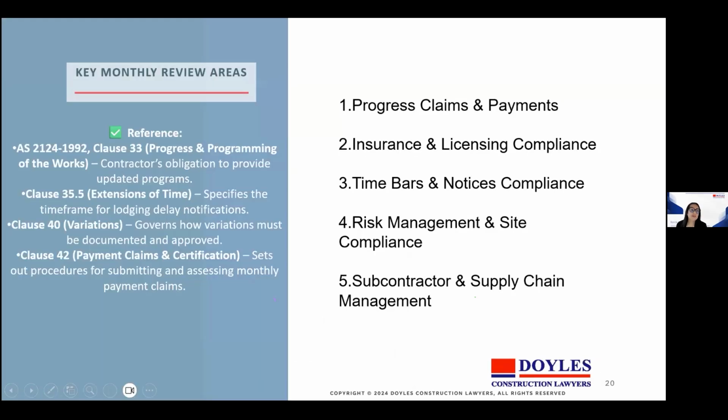So just moving on to key monthly review areas. We've identified 5. Progress claims and payments, insurance and licensing compliance, time bars and notice compliance, risk management and site compliance, and subcontractor and supply chain management. These 5 areas represent where most live project disputes originate.